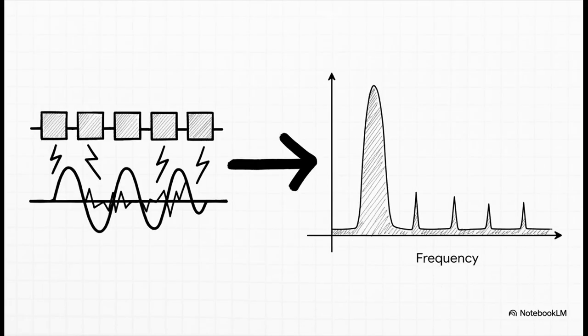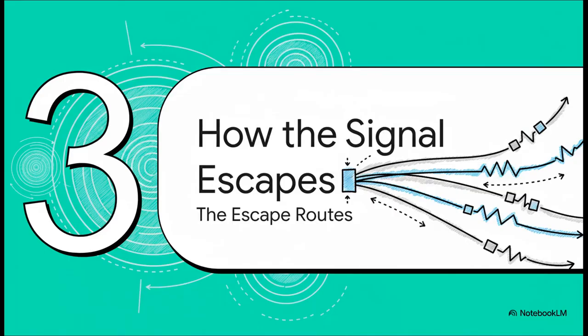So here's where it all comes together. When the energy from these digital bits, which we now know is pure harmonic content, couples back into our sensitive analog path, well, we no longer have a clean sine wave. You can see it clear as day on this FFT plot. The corrupted signal now has these very distinct spurs right at the harmonic frequencies. See? This isn't random noise, it's harmonic distortion, and its fingerprints point directly back to our digital lines. Case closed.